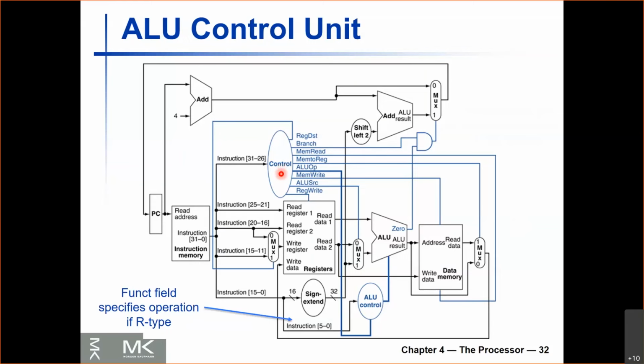I don't understand how you want to lessen the hardware. I'm not sure I understand your question. What we do when we have an R-type instruction is we specify the opcode corresponding to the R-type instructions, and we specify the funct field to determine what the operation is.